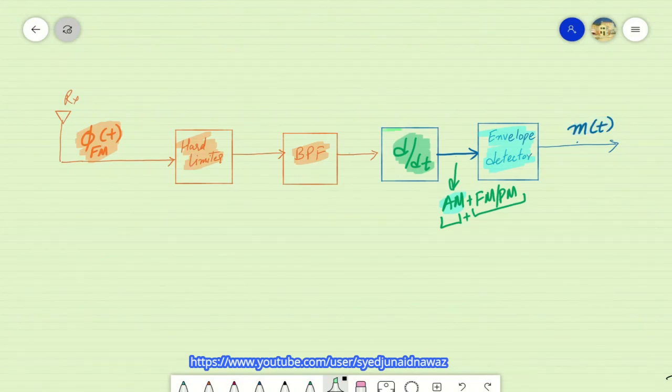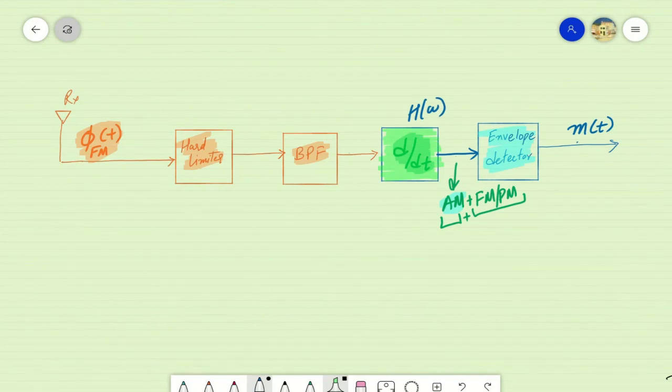Moreover, we have also seen that this differentiation operation can be realized through different methods, where employing two parallel Gaussian filters to achieve the response equivalent to differentiation is a popular type of this class of demodulators, referred to as a balanced discriminator. So this is the slope detection method to demodulate the information from received frequency or phase modulated signals.